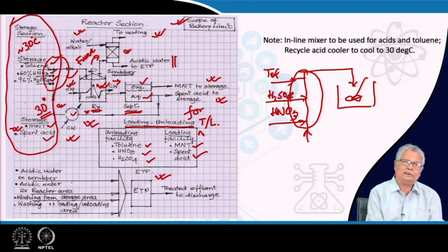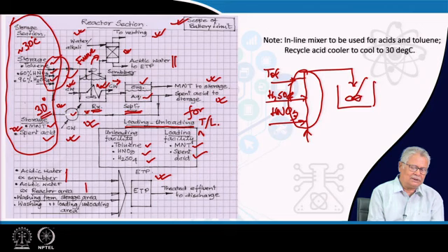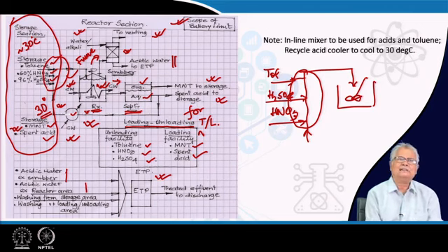So, the streams coming to the ETP will be the acidic water which I have just mentioned from the scrubber. See, you have a reactor which handles a good amount of acid. So, there will be some amount of leakage and spillage, and the water which is used for washing in that area will possibly be acidic as well.